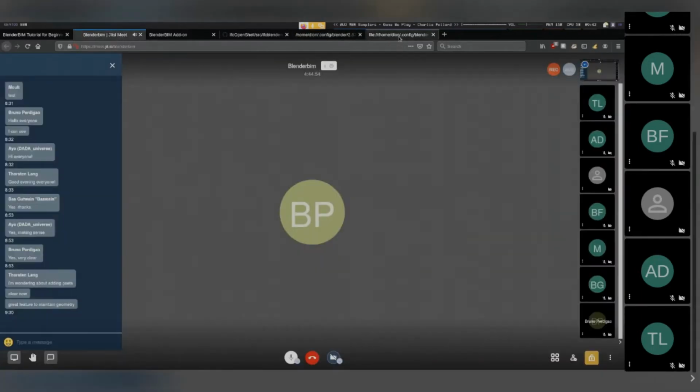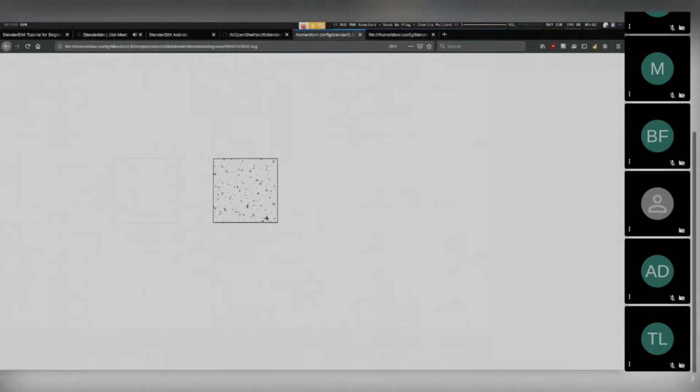So it's quite a powerful system, and it's also queryable. You can actually write XPath code which can say, hey, show me all the documentation which has this element in it, or show me all the documentation which has concrete in it, or check that all the spaces in this documentation also have a fire-rated wall or something like that. So it's quite a powerful feature that you can actually query documentation as a data set, that you can't do with the traditional way of doing things.